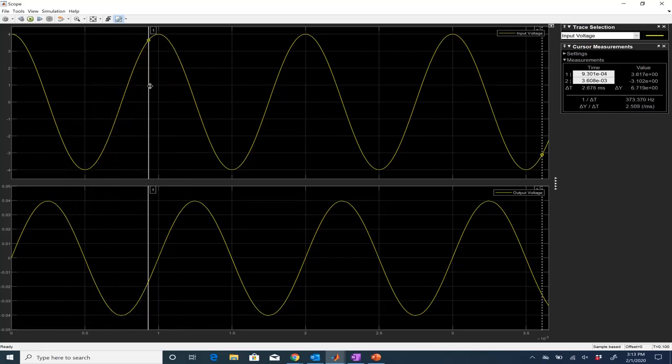Alright, I'm going to pull this guy. I'll set him right here, right at the peak of that waveform, as best I can get it to the peak at least. Okay, and I see that I got it pretty close to the peak. It says the peak value here. So the number 1 and 2, it tells me right now that my cursor is located at time 9.964 times 10 to the minus 4, and the value there is 3.995 volts.